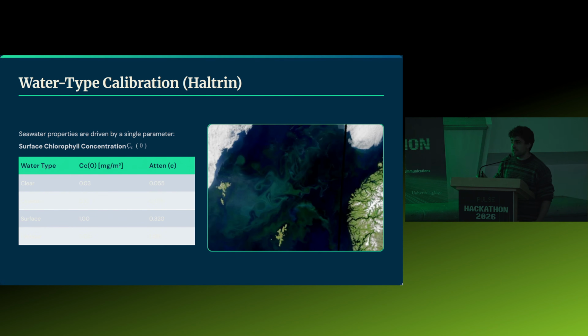And not only can you get your bit error rate once you have selected your hardware and you have your power and everything, but you can also select a maximum bit error rate, for example, and backtrack and see what power you need. You can also see for each decibel difference in your link budget how many meters you are gaining or losing. So that's also quite interesting. A thing you cannot do normally with Monte Carlo because you will need to simulate each different situation. If you want to change the depth or anything, you need to simulate it again.